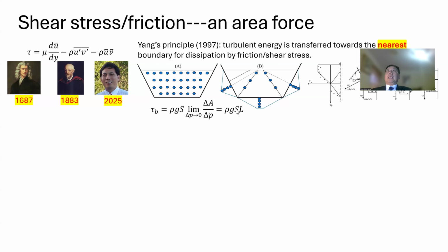So the boundary shear stress is proportional to the normal distance from here to the surface, or from here to the division line. So we have this curve. And similarly in the vertical, in this region, the normal distance is the vertical line, and the stress will be proportional to this distance. We will have a distribution like this.